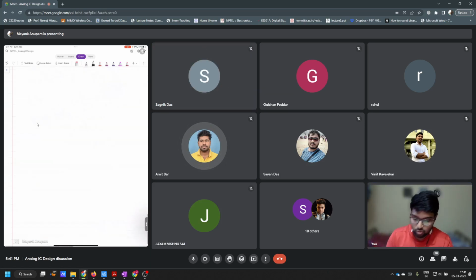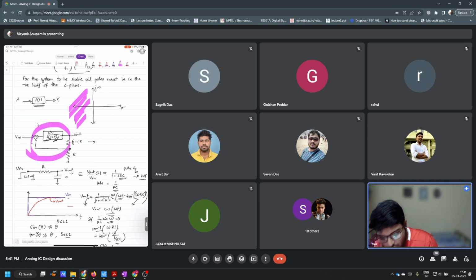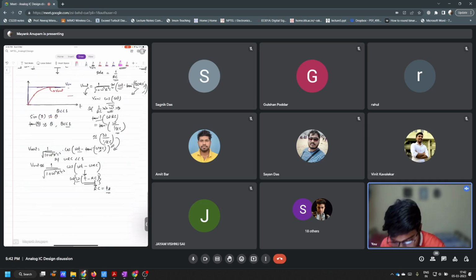This is why in your lectures you learned that when we have poles in the overall feedback system, it can be modeled as some delay. Basically it acts like a delay in the feedback system, and you know that when you have a delay in the feedback system, the system has a tendency to become unstable, right? So the extra poles that you add in the system are going to cause a problem of instability in the system. That is what you saw.